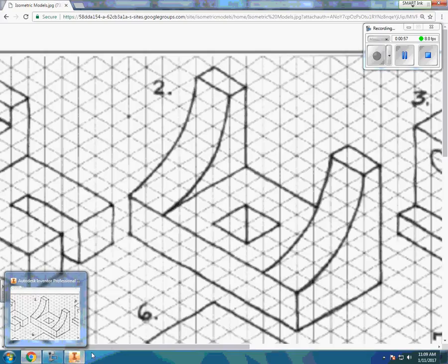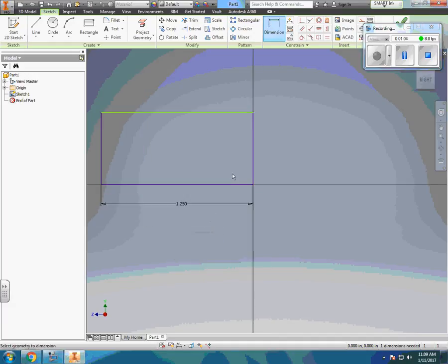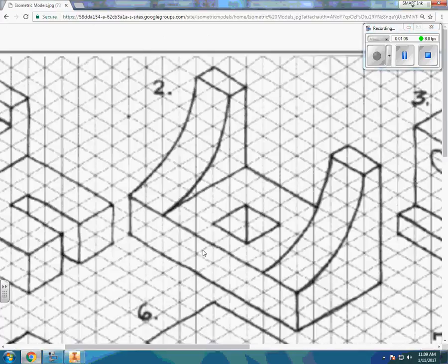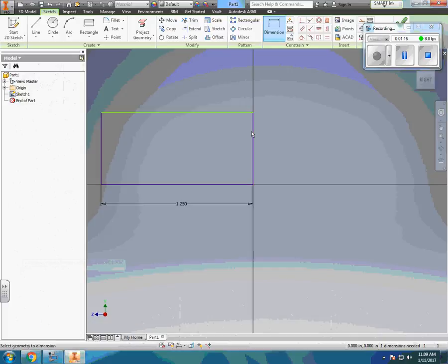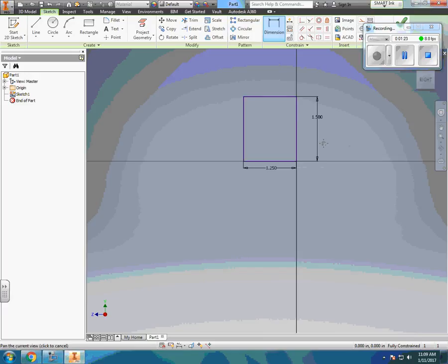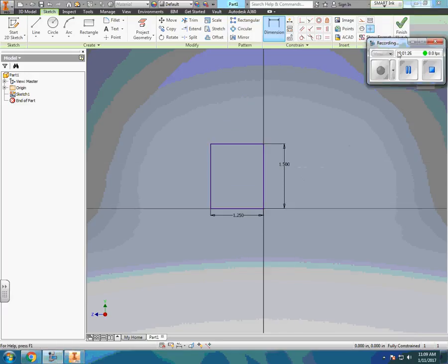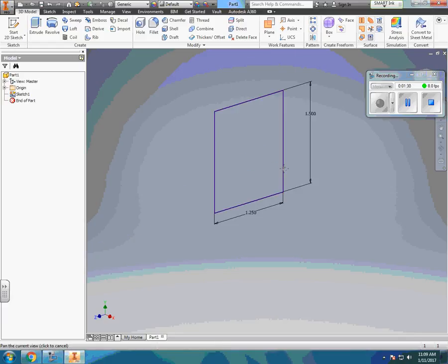So we're looking at setting this dimension to 1.25. Now I need the height of this block. So I'm going to count 1, 2, 3, 4, 5, 6. 6 blocks times 0.25. So here's a little neat trick. I can take 0.25 times 6 and it's set at 1.5. Once I'm done setting my block, I'm going to finish sketch and I'm going to create my block.